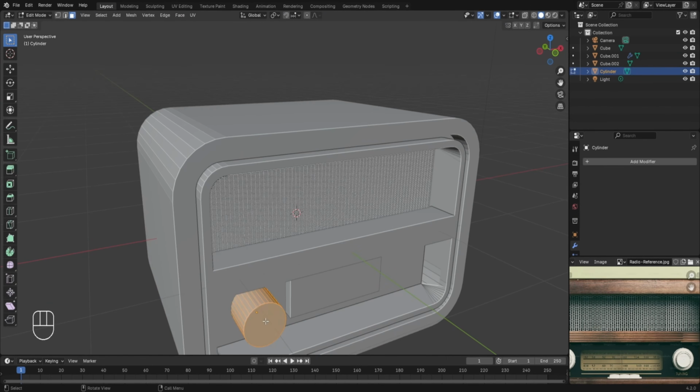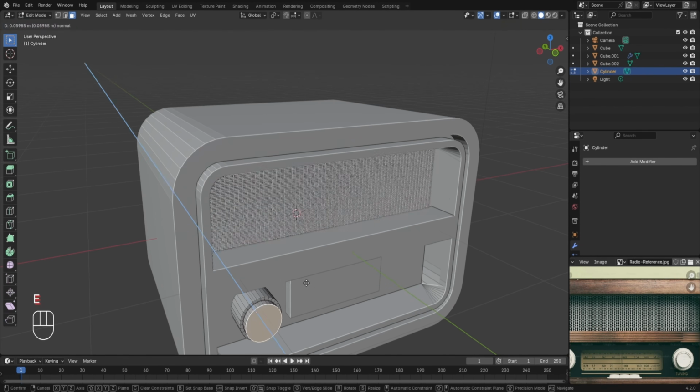After this, let's change the angle, and once all the adjustments are made, we'll press Tab to enter the edit mode. Then with the face select mode enabled, I'll select this face. Let's push it slightly inwards by pressing G and Y, and for this rotating part of the control, press I to insert the face, then left click, and we'll extrude it forward like this.